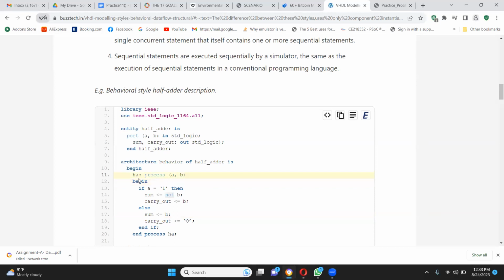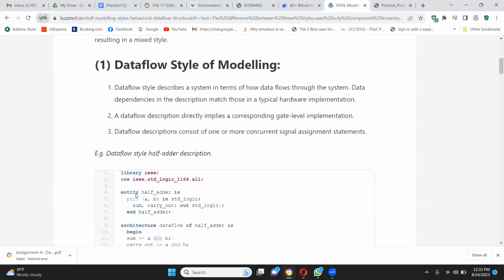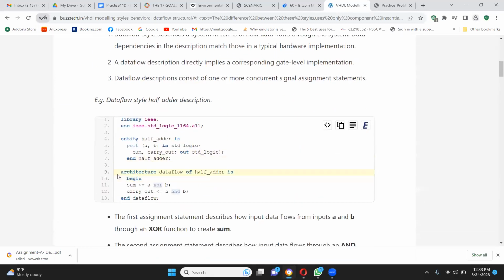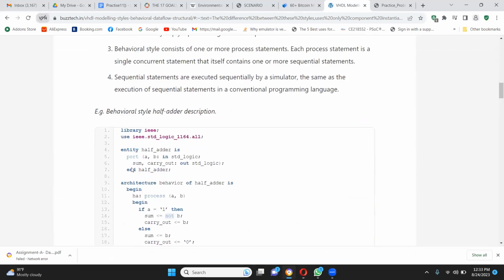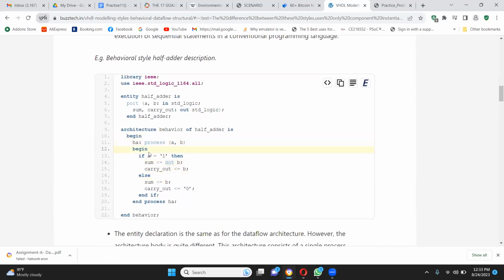If there is no change in A and B, is there a need to execute the process? No, right? But in case of data flow modeling, this will always be executed. When I give an input, this will always be executed. But in the behavioral model, the process begins...